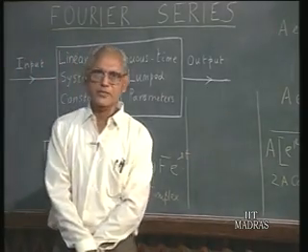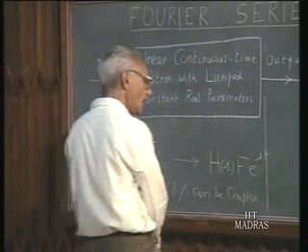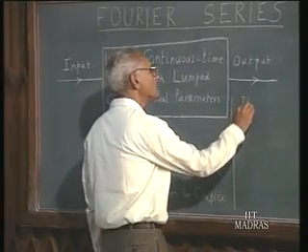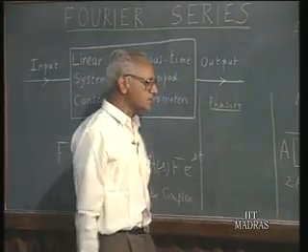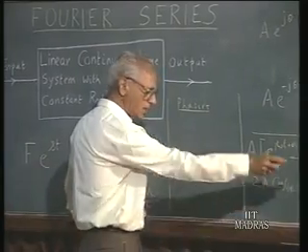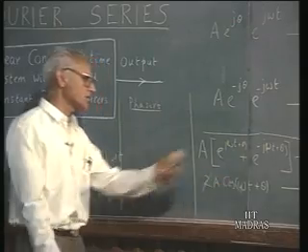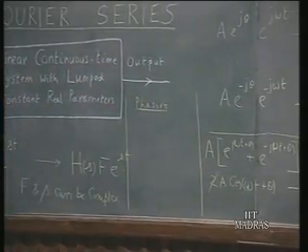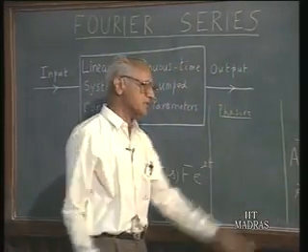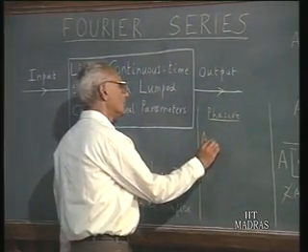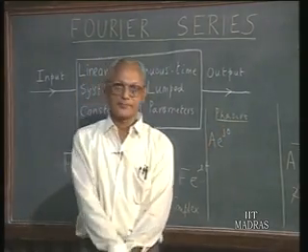Normally, when we deal with sinusoidal functions of time in AC circuit analysis, we use the phasors. Let us see how these are related to the phasors. In terms of phasors, we express this. Now that we have got this expression, I can drop this 2 here and this 2 here and simply deal with A cos(ωt plus θ). Because after all, if this is reduced by factor 2, output also will be reduced by factor 2. The phasor for this, as you recall, will be written as A e to the power of jθ, A at an angle θ.